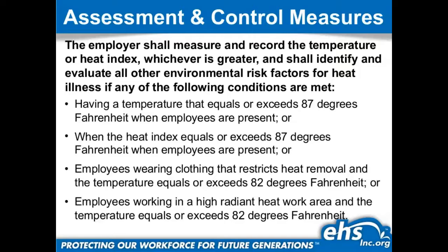With that as well, as I stated before, maybe one side of the building does meet that temperature requirement. Maybe the opposite corner, in which there is radiant heat coming off of machinery and equipment, exceeds that temperature. Those factors should be taken into account. More than just stepping out of the office, stepping into the work environment briefly and doing one quick measurement. Those measurements should be done throughout the building to get an idea of where temperature differences are happening.